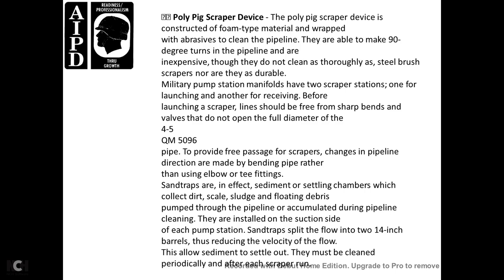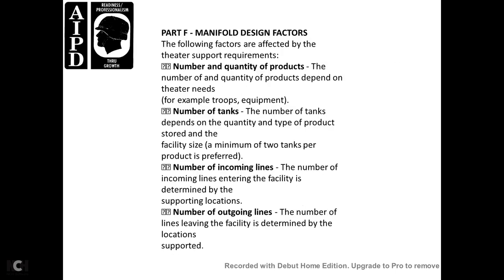floating debris accumulated during pipeline cleaning. They are installed on the suction side of the pump station. Sand traps flow into two 14-inch barrels to reduce the velocity of the flow, and this also allows sediments to settle out. They must be cleaned periodically, after each scraper run.